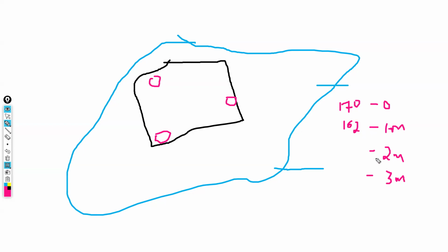But when you went to 2 meters, it became 185, and maybe 190 at 3 meters. So these bearing capacity results, you're going to get them for this trial pit, the next trial pit, and the other trial pit.